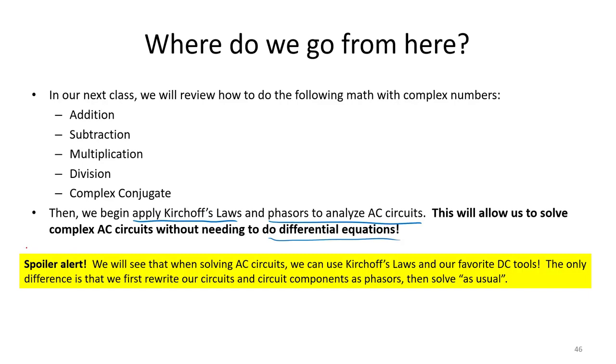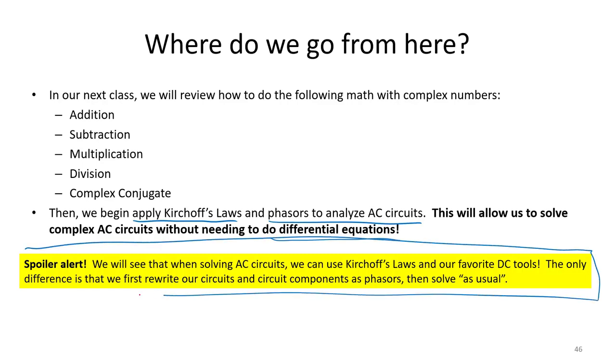And so, just as a spoiler alert, we're going to see over the next few lectures that when solving AC circuits, we can still use Kirchhoff's laws and our favorite DC tools. The only difference is that first we have to rewrite our circuits and all our circuit components as phasors and something we call impedances.